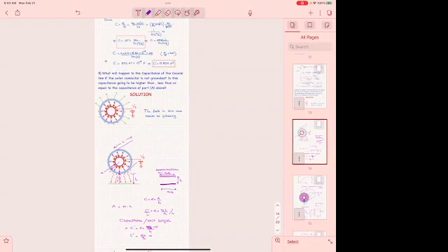The other is a hard connection, where you go and solder the ground, and then the soldering is not very good. It was either not done symmetrically, so only a teeny point of solder connects to the other side. So there are a lot of things that you have to check.